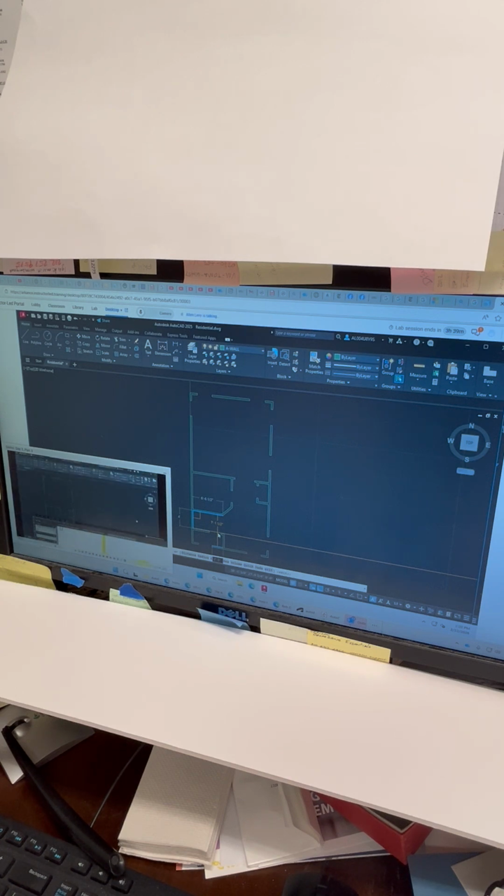Do the math. 8'3" plus 6 is 8'9". 8'9" plus 3.5 inches, and that's the thickness of this wall, is 9 foot, and the 1/2 inch left over is the remainder. So it added up all of those dimensions to get us that 9 foot 1/2 inch dimension.